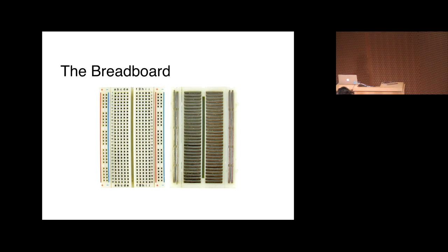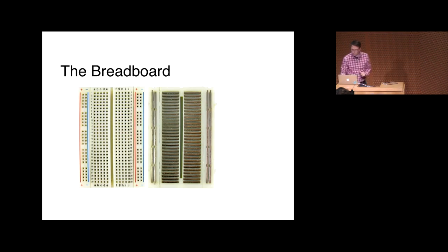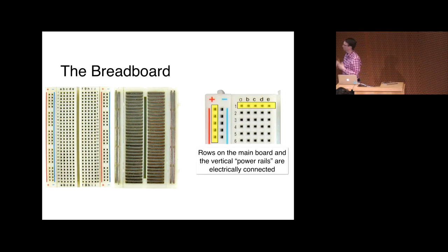So a breadboard has many holes, but underneath those holes you have connectivity. Horizontal rows are connected until the middle strip. And then the power buses for power and ground on the sides are vertically connected. So anything you plug into the same row gets internally connected.